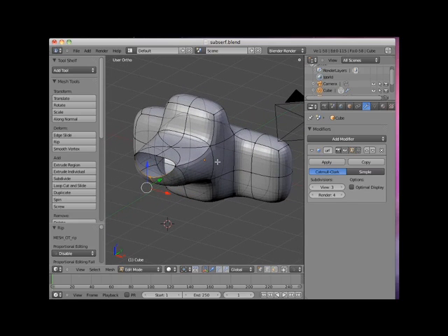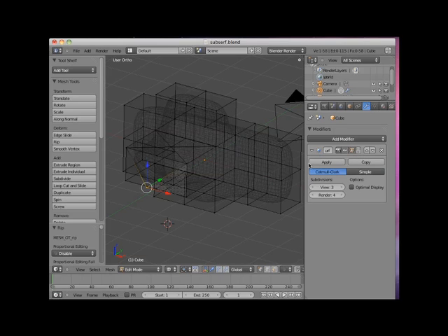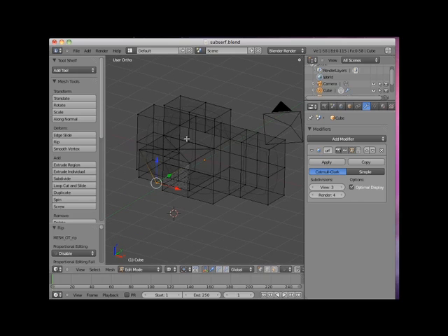There's a checkbox in the Subsurf modifier panel called Optimize Display. This feature is applicable if you are in wireframe display mode and the editing cage is turned off. Here, if the Optimize Display box is checked, it will not display the subdivided surface.